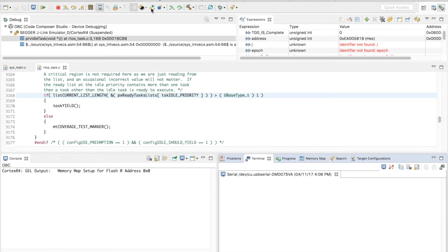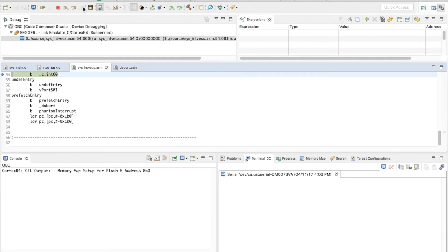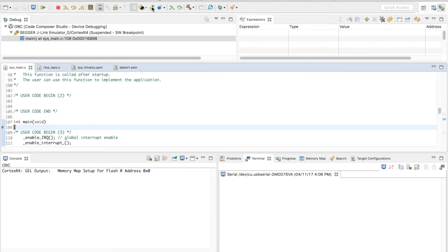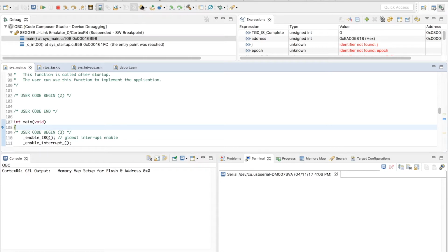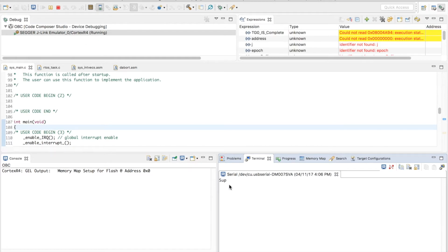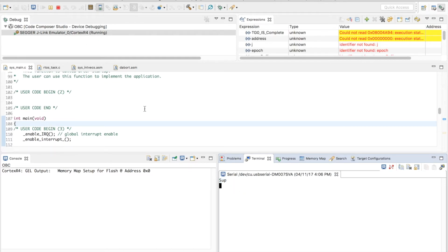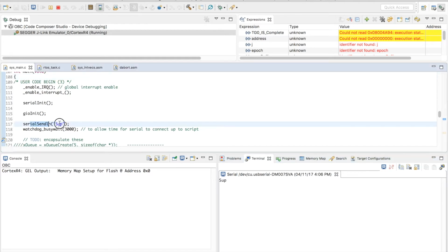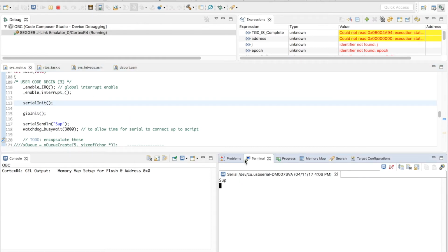I'm just going to restart the code. So what I did here is I reset and restarted the code. So I've got my serial port connected. Now when I click start, I can see it's printing something. This is just what I have told it to print in this initial code. The code you happen to clone might be different, but it will likely say something right when it starts up. So this lets you confirm that your connection is working correctly, which mine is.